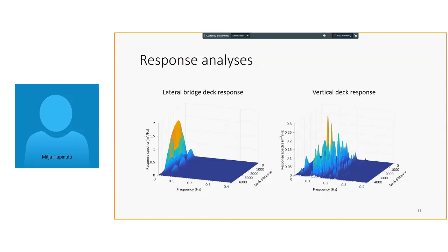It's not the convolution itself, but repeating the convolution 30, 40, 50 times, because inside one time step we have to repeat it 40 times. We did this by splitting those convolution integrals into two areas. One area is everything that happens before, which we save into a value, and then we just calculate the small area that is changing inside the new mark. I think this improves the efficiency of this algorithm by up to 50 times.